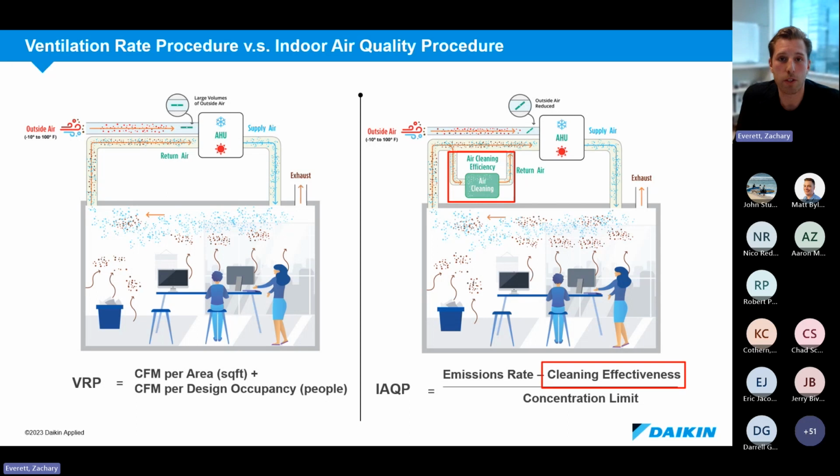In most cases, no, because we still have exhaust air. We're not treating all of our air. We're still exhausting, so we have pressurization requirements. But short of those pressurization requirements, yes, we can remove almost all of the outside air in theory. In practice, that's not always the most fiscally responsible move, right? So this air cleaning does cost money to put in, and there is a break-even point at which it no longer makes sense to create, for example, the cleanest air in the world, because beyond a certain threshold, this isn't making a difference to the end user or the occupant specifically.